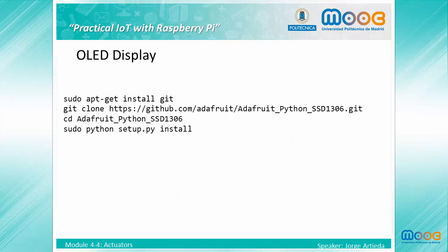We are going to use a driver from Adafruit to interact with our display. We download it from GitHub using git clone. If we haven't installed Git previously, we can install it with the apt-get command. Then we build and install the driver using the setup Python script.